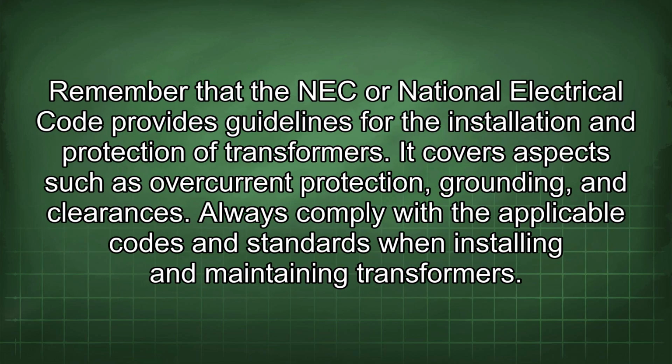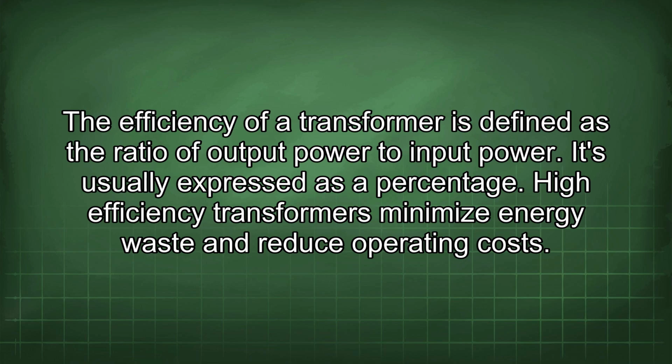Remember that the NEC, or National Electrical Code, provides guidelines for the installation and protection of transformers. It covers aspects such as overcurrent protection, grounding, and clearances. Always comply with the applicable codes and standards when installing and maintaining transformers. The efficiency of a transformer is defined as the ratio of output power to input power. It's usually expressed as a percentage. High-efficiency transformers minimize energy waste and reduce operating costs.